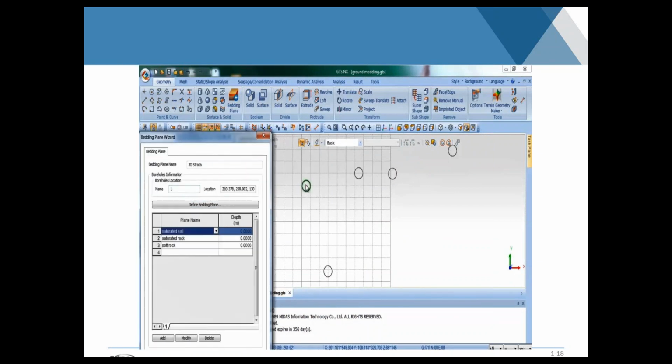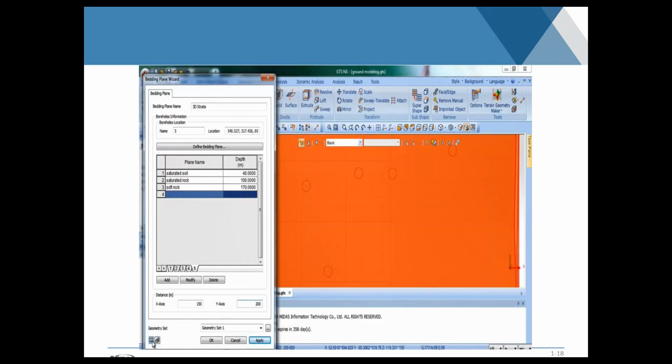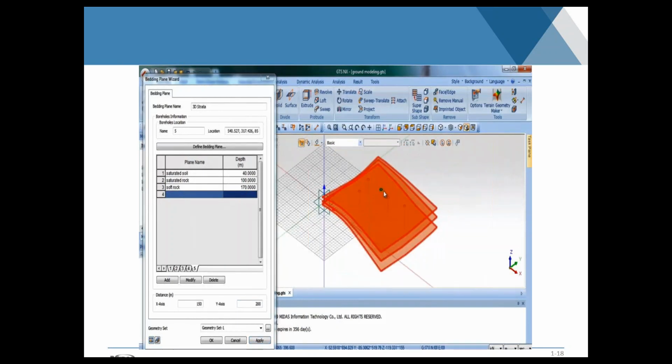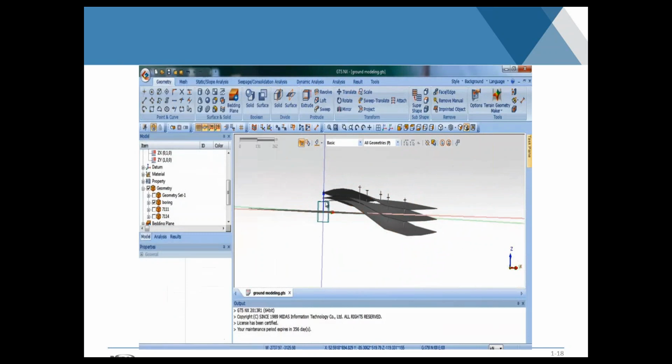the point of drawing these lines is that I can just click on them in the program, and then jump right into telling the program that at this depth I have the first layer, the next layer is at 70 meters, the third layer is at this distance, and then follow that in sequence until I have, in this case, the five boring log data input, and the program will then interpolate that into surfaces.